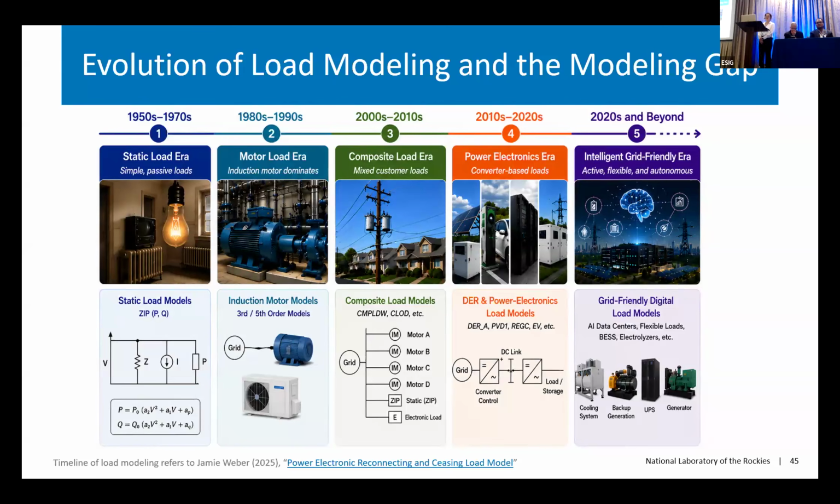And back in 1996, after the famous WECC blackout, we start to think of the WECC, a lot of utilities in the WECC are making a lot of efforts to have this composite load model in order to capture the more accurate load response dynamics. And when we are thinking about recent years, we also added a lot of good load data there, including the EV model developed by EPRI and the DER_A model and a lot of those types of models.